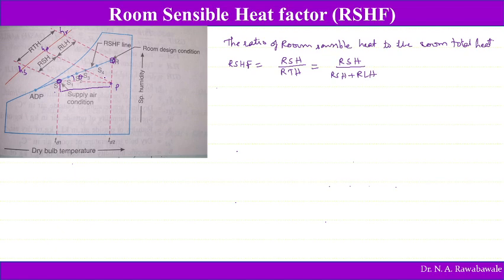So thus supply air, having its condition given by any point on this line, will satisfy the requirements of the room with adequate supply of air. In other words, supply air having conditions marked by points S1, S2, S3 and S4 etc. will satisfy the requirements. The quantity of air supplied will be different for different supply air points.